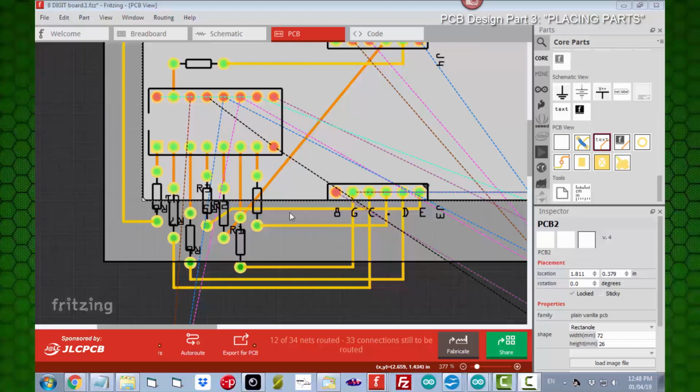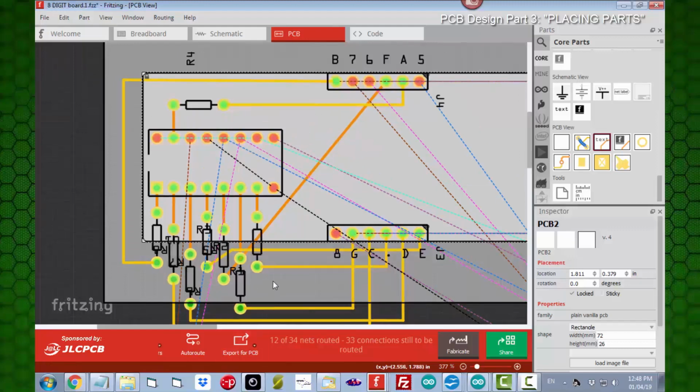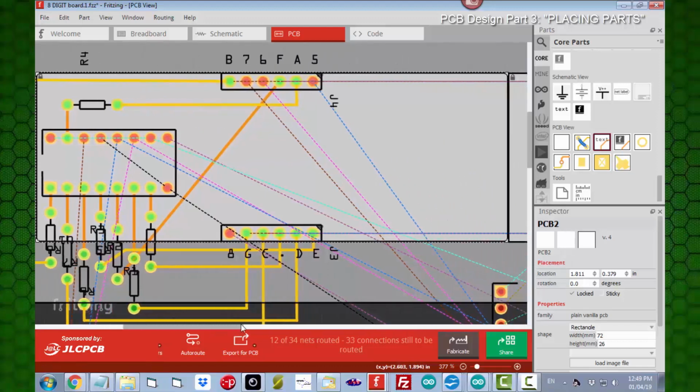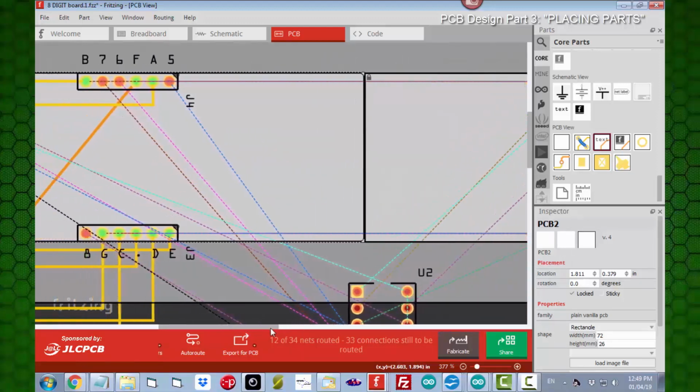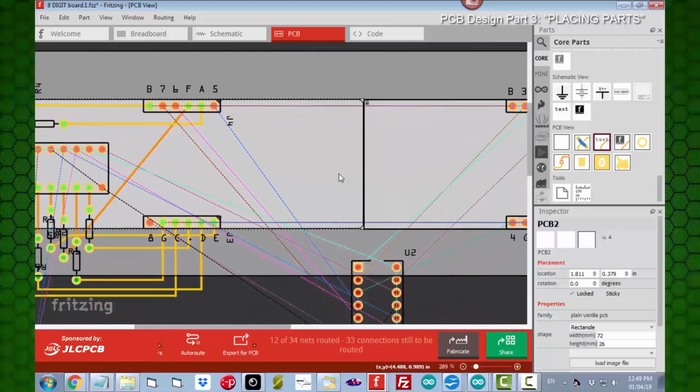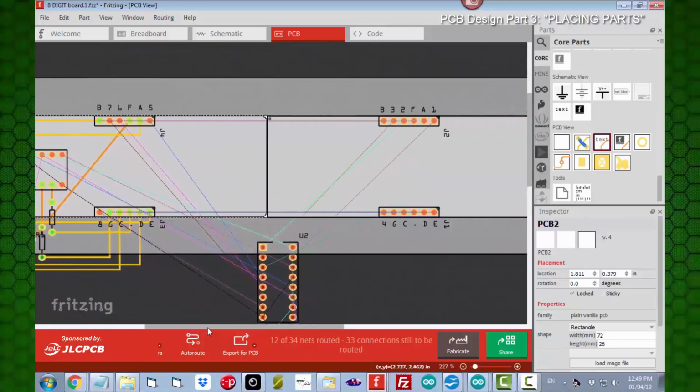One of the things that you'll notice though is that we have run all of these current limiting resistors over to the headers on this panel here. They will also need to go on to the other panel. Let me scroll back here and I'll show you that if I come over here and touch on this guy, right, well, let's do it on the resistor end, it might be easier, the G lights up on both sections. We need to run a connection between those two. So let's do that now.